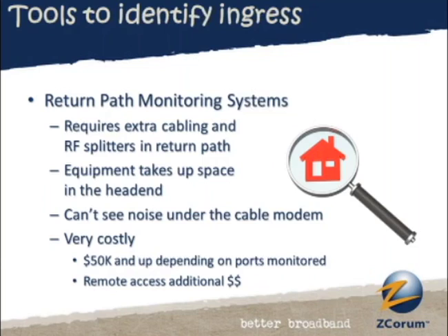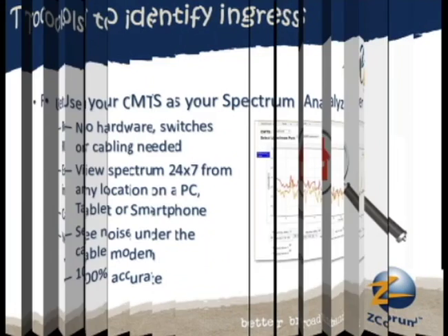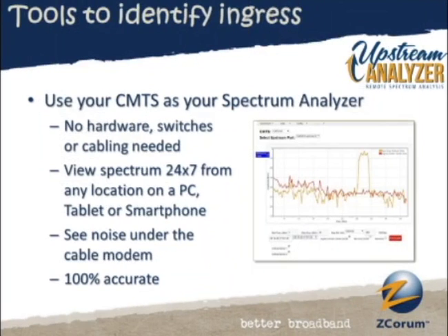And again, because of the cost, a lot of times they don't monitor all of their channels, right? So that brings us to really the topic today, which is how you can use your CMTS as a spectrum analyzer.